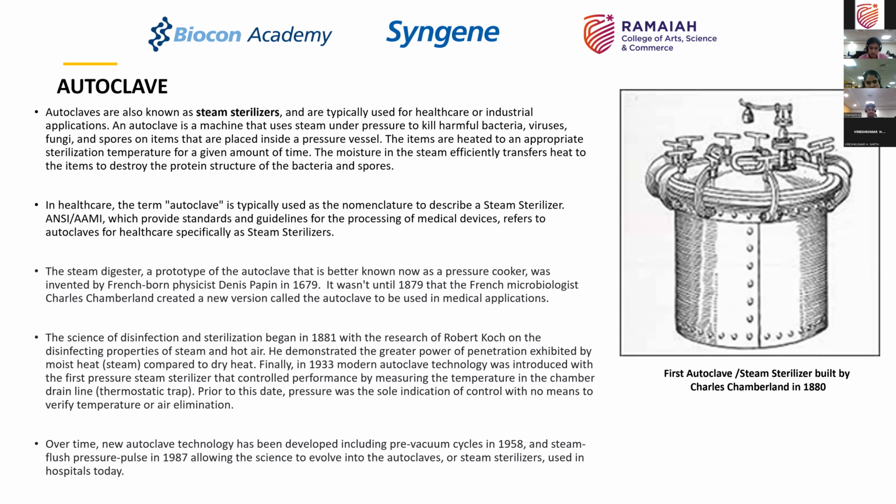Finally, in 1933, the modern autoclave technology was introduced as the first pressure steam sterilizer that controlled performance by measuring the temperature in the chamber drain line. Prior to this date, pressure was the sole indication of control, with no means to verify the temperature or air elimination. We have discussed in the past that removal of air is important, temperature is important, pressure is important. Even in your residence, when you use a pressure cooker, you don't measure the temperature, right?